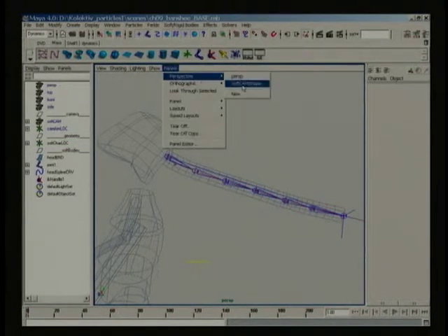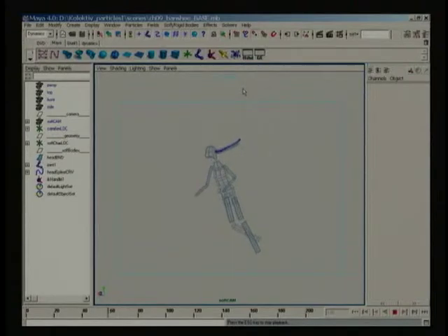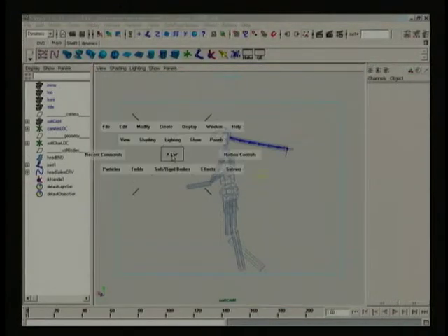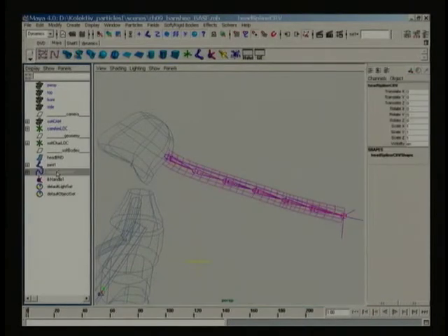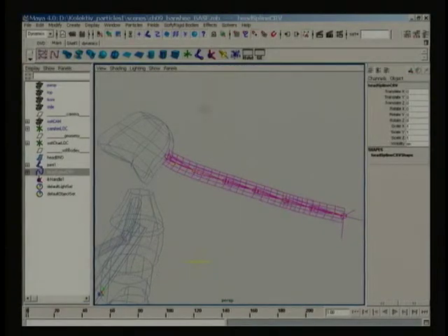All my CVs have a goal weight of 1, causing the strap to look rigid and non-dynamic. I want the tail end of the geometry to flap in the wind behind the character, which means I need a high goal weight for the first 2 CVs particles near the head, and a gradually decreasing goal value as the particles get further away.